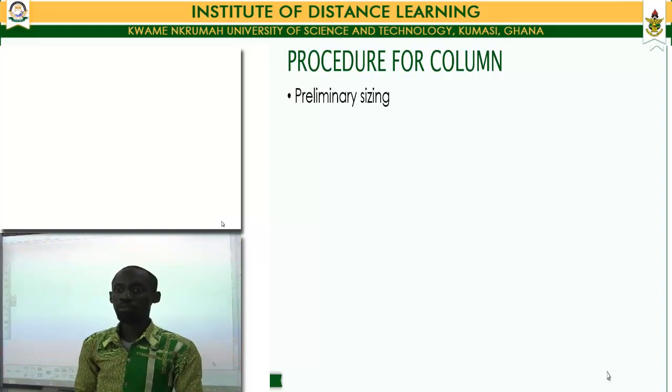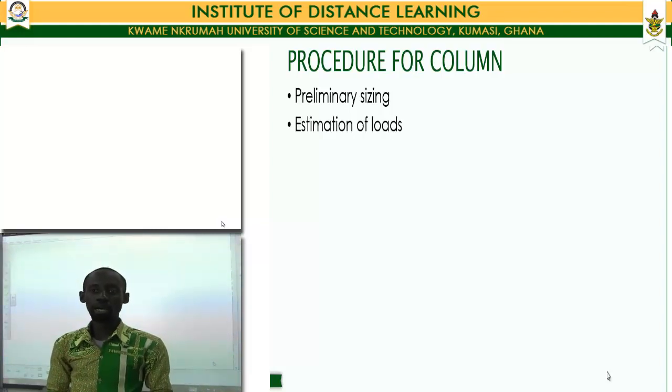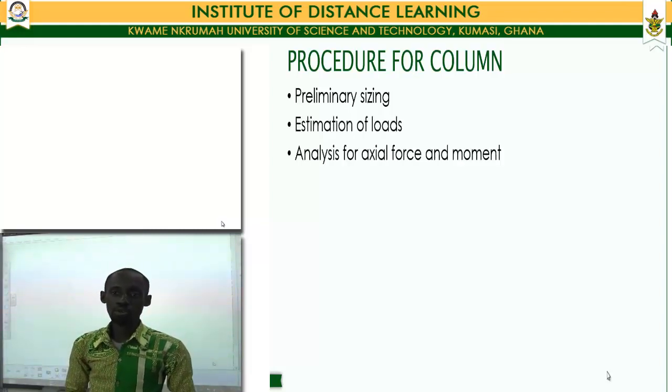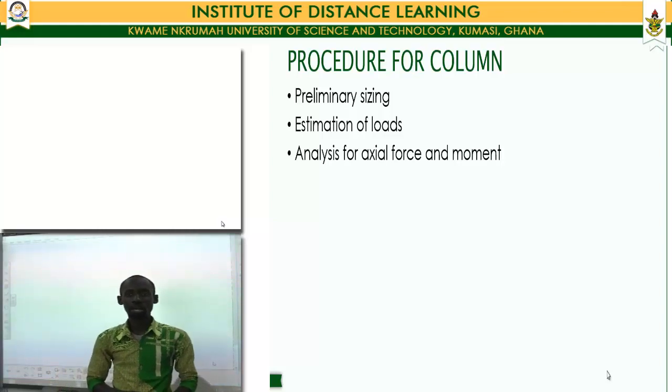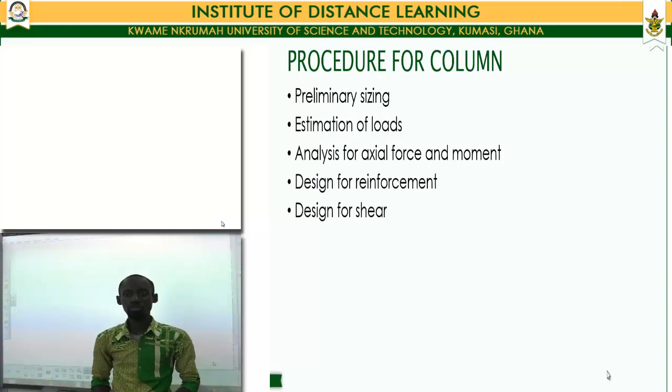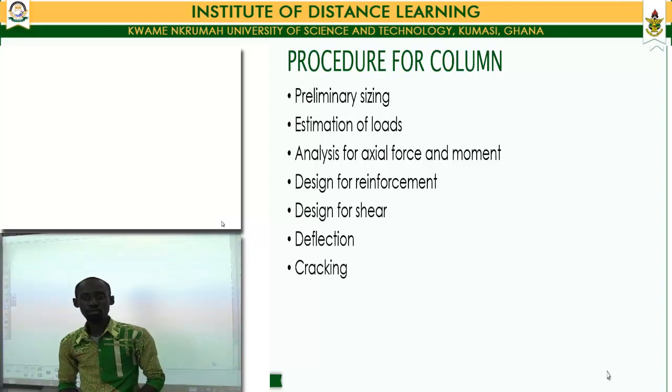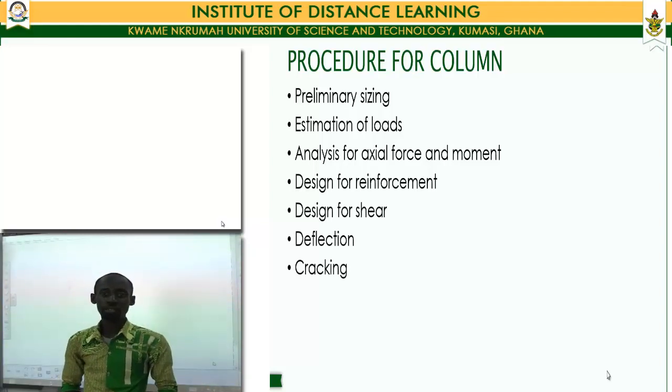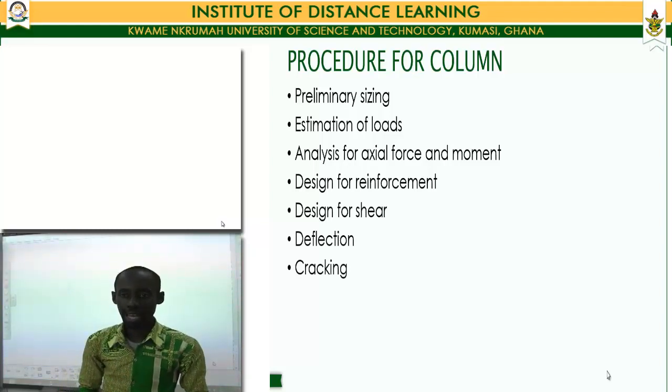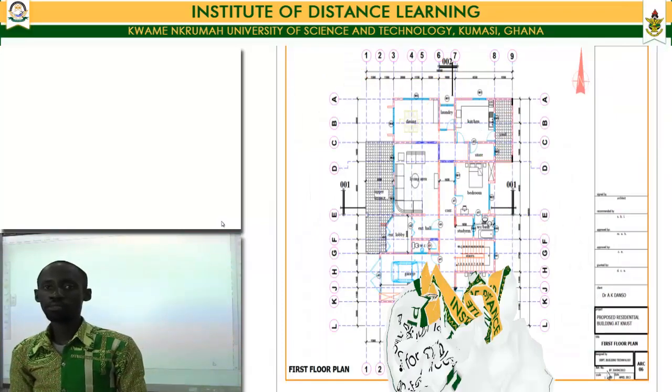For the procedure of our column design, we'll start by doing our preliminary sizing. We'll estimate our load, analyze our columns for axial forces and moments, design for reinforcement, design for shear, check for deflection and cracking, and ultimately we do our detailing for our column.